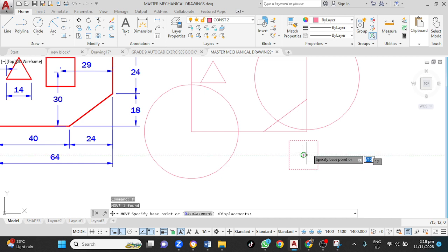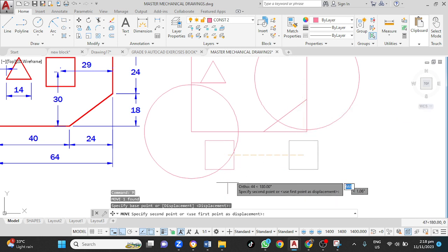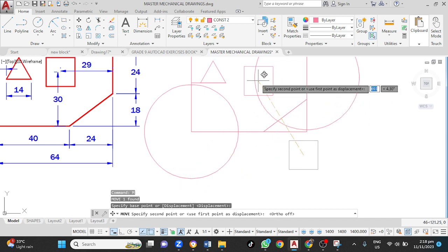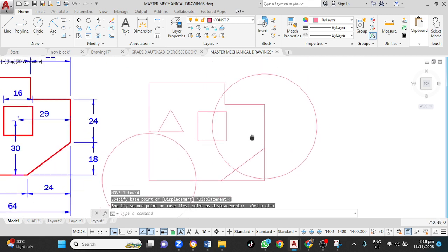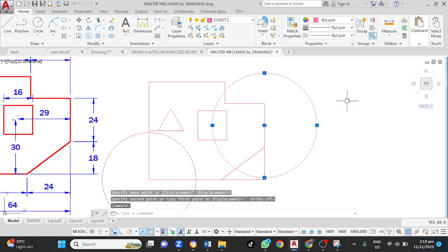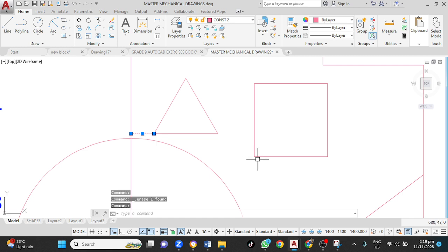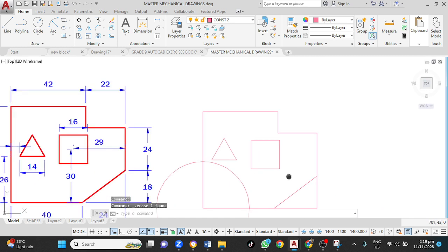So I left click here, and it is important to note that this midpoint center point only pops up because I turned that on while setting up. So I left click here, drag that, deactivate my orthogonal mode, go up to here and left click there, and that is now done. I could now delete this, and also delete this and then brighten up.